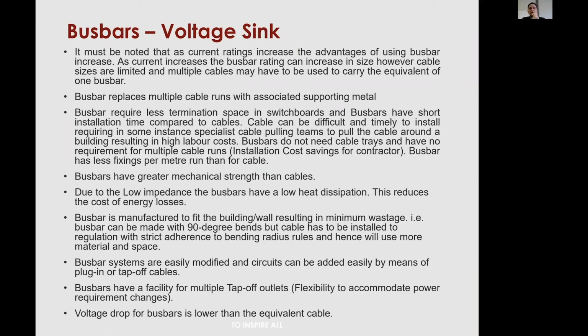So what I actually see is quite common is on that fuse box that people use to protect the batteries, they might connect a little piece of DC cabling to the next fuse pull box, and in that manner they deem that they've connected positive to positive, and they've created a virtual bus bar.